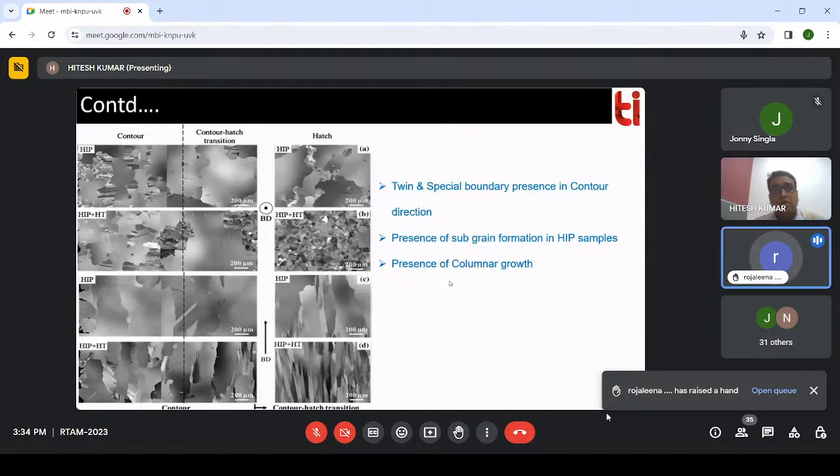And for defect analysis, what software is used? For defects, you can use X-ray to calculate the defect density. Those kinds of characterization techniques you can use. Other than that, EBSD also gives you the geometrically necessary dislocations in your sample. Those facilities will be quite helpful if you want to calculate the defect density in your material.